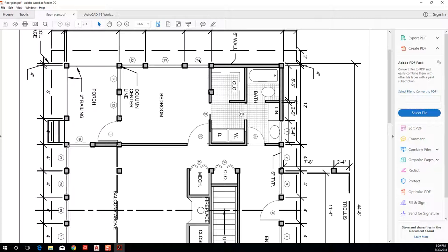Call out, essentially. Yeah. So I think this is above and beyond, but normally if you have a tag that says 24, you're going to go to the window schedule and see what window number 24 is, right? Then maybe your school of thought is, I don't want to call it out with a tag like that because the type of projects I do don't require that type of annotation. So we're going to call it out with a leader, right? And say, this is a 24 by 24 inch window, 36 inches off the ground. And then there's a third way of doing it, where instead of a tag with a number, you could just do a string of text above it that says it's a 3030 with a 36 inch sill or whatever.